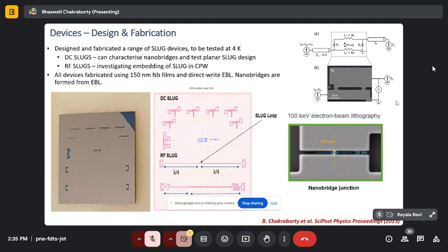The idea was that the axion particle, when it comes close to a strong magnetic field, actually converts to photons. Now these photons are a very weak signal. So in order to amplify those signals at a very low temperature, we need something as an amplifier. Those sorts of amplifiers have been a topic of research. So I tried to fabricate this quantum sensor, which was based on a Josephson junction. This Josephson junction is basically a kind of amplifier. We can consider it as an LC amplifier sort of thing.